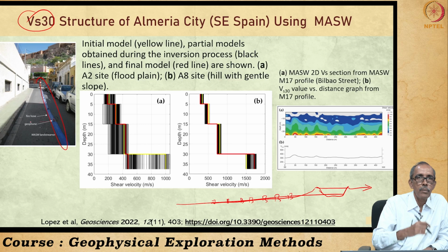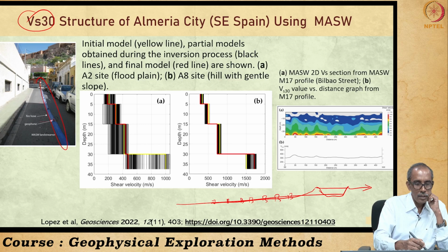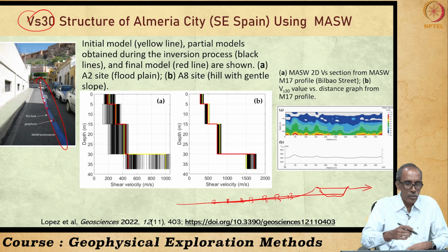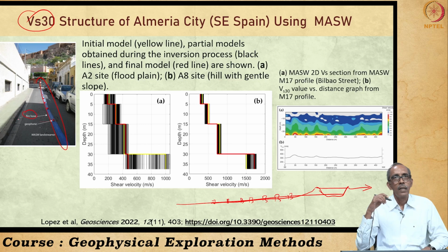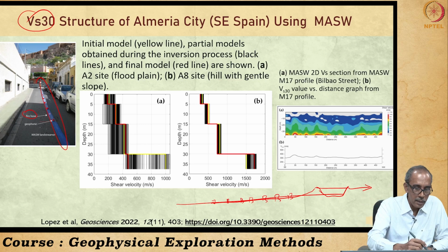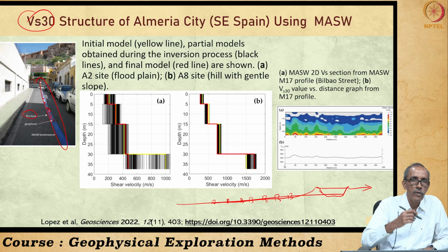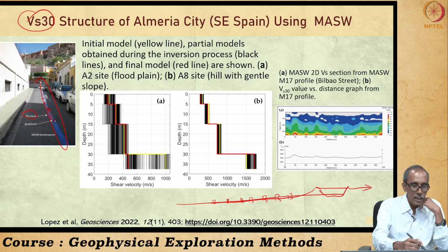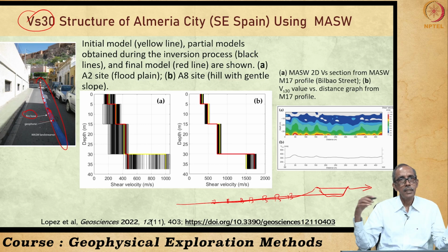Same thing is also possible on the land by having the geophones fixed on some kind of cables or tubes. Usually here they are using a fire hose. Why are we using such a hose? The energy may not be transmitted within the hose, right, because these hoses are energy absorbers, right. So, whatever shock received by the geophone here will not be transmitted, because it is a kind of flexible pipe,